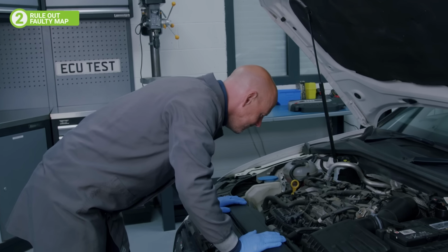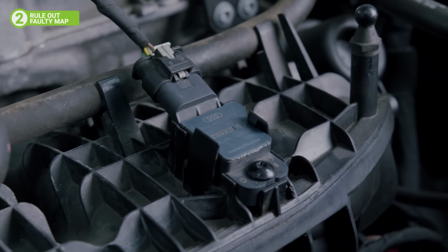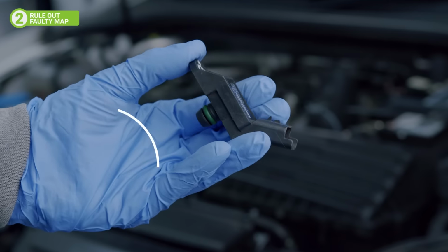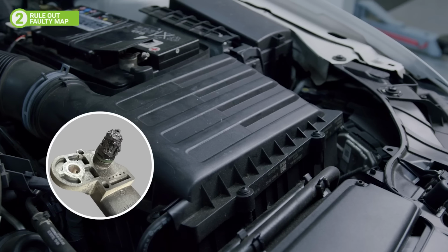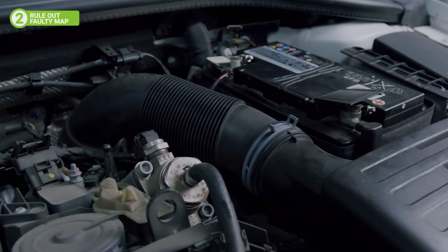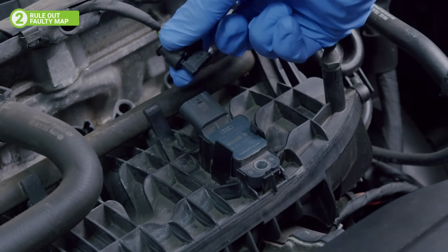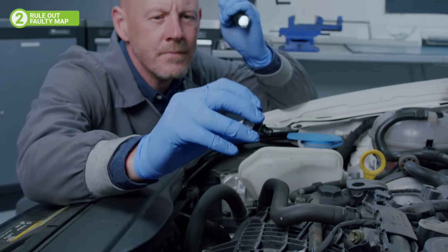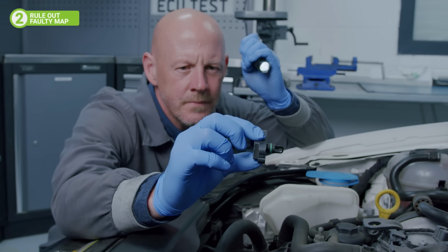Unfortunately, MAP sensors can develop issues over time. One of the most common is clogging from carbon buildup, dirt, or oil contamination from the intake system. Before starting any electrical diagnosis, remove the sensor and ensure the tip is clean and clear of any contamination, and clean it if necessary.